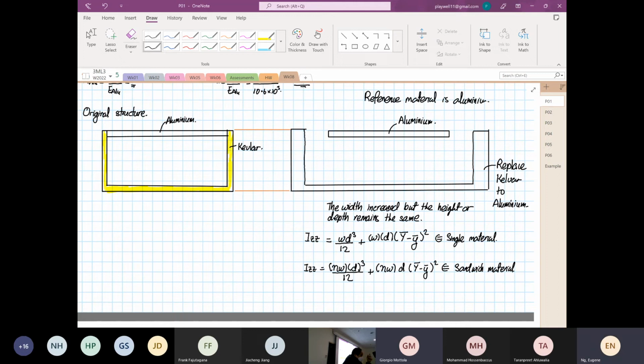The next reason is why is it like that? Why don't we increase the depth and make the width constant? The problem is with this equation over here. Depth cubed. What is the problem with that equation over there? Let's say now, hypothetically, okay, I'm going to write on the left-hand side, we allow the height to change.